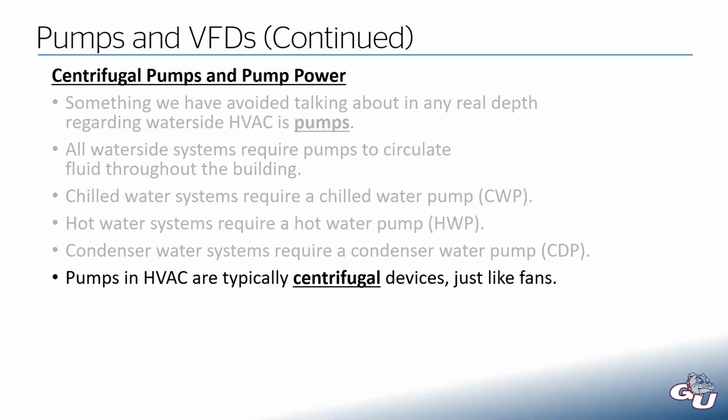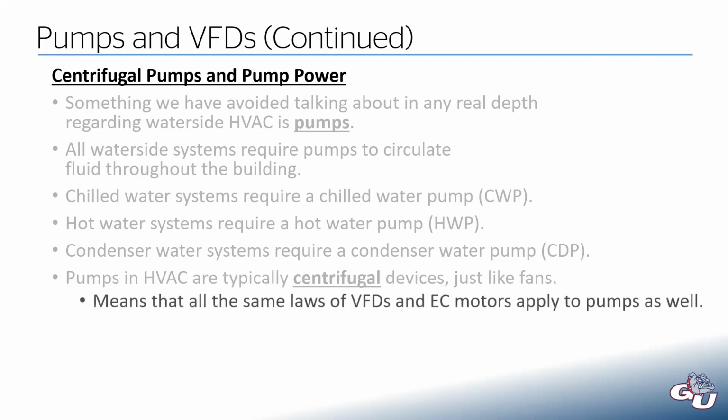What this means is that all the same laws of VFDs and EC motors, the affinity laws and what happens when we change the speed of a fan or a pump, all of those same laws apply because fans and pumps are all centrifugal devices.